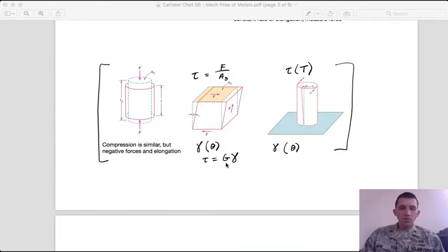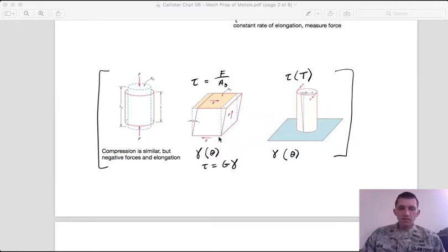And like we saw before, right, there is a proportionality constant between the shear stress that we apply and the deformation that we observe, right? So here we call it G as opposed to Young's modulus, but the idea is very similar. And we can also, instead of having a shear component like this, put the sample under torsion, where we are twisting it about an axis of rotation, and again measuring this angle of deformation in regards to some applied torque.